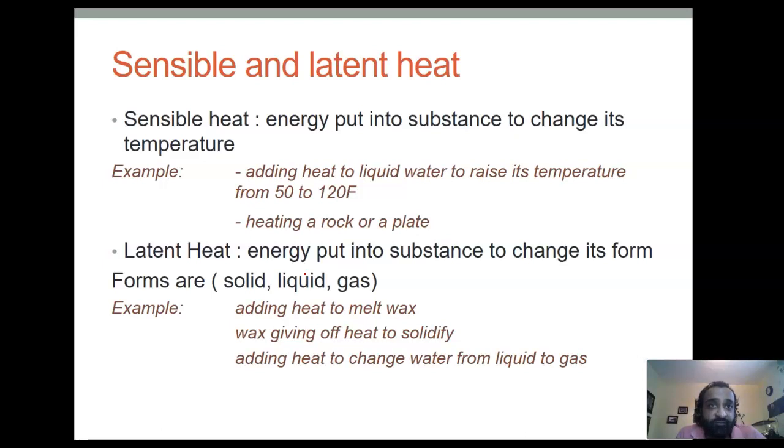The air has a lot of vapor in it, and it has a lot of latent heat, and there's also something called the dew point. So if you turn on the AC on a humid summer day, the temperature is 90, it's very humid, humidity is 70%, the AC will try to cool the air, but in the beginning it's going to collect all the vapor from the air, turn it into water, and reject it outside before we reach the dew point.